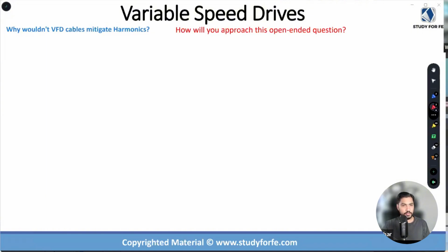They are specialty cable, and the manufacturer, Siemens or Eaton or ABB, whichever drive you are purchasing, they will always tell you that we need the VFD cables, or else potentially your warranty can be void. Okay. So VFD cables are a real thing.